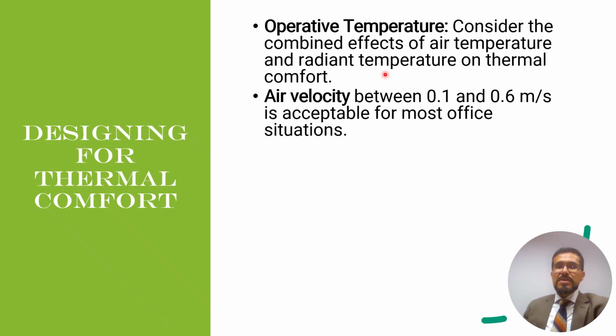Then the air velocity also needs to be maintained in a range between 0.1 and 0.6 meters per second. Lower velocities than this range will create an environment that could feel too stuffy, and over this range it could create drafts that are uncomfortable.